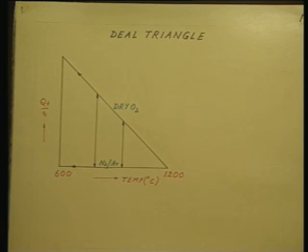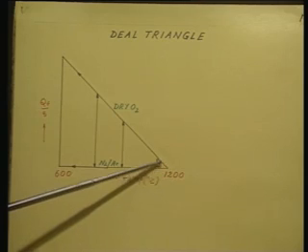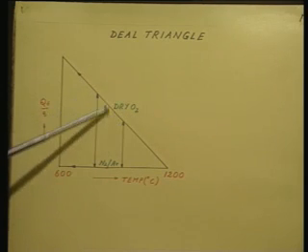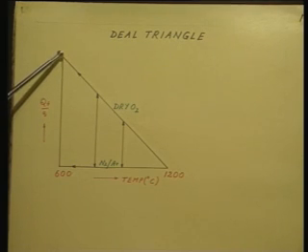Now, let us say that the oxidation is taking place at a very high temperature, 1200 degree centigrade, and now from this temperature the sample temperature is being lowered, and while reducing the temperature still an oxidizing ambient is being maintained. Therefore, there is the possibility of having incomplete oxidation. So, this is the path it traces. As you reduce the temperature, if it is done in dry oxygen ambient, this is the amount of fixed oxide charge you get, which is very high, greater than say 10 power 12 per centimeter square.